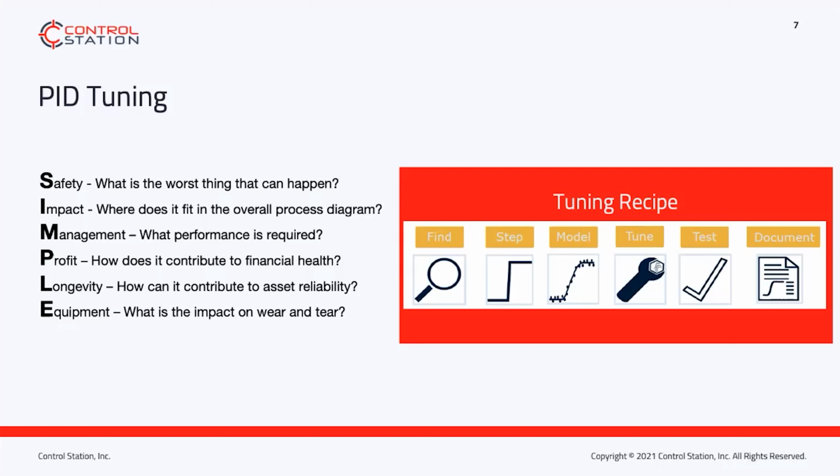What are the economic factors associated with this loop? Energy consumption, valve wear and tear, and throughput. And lastly, it's longevity of equipment. They're more or less the same. The more aggressive parameters you provide to the controller, the more wear and tear it can cause.